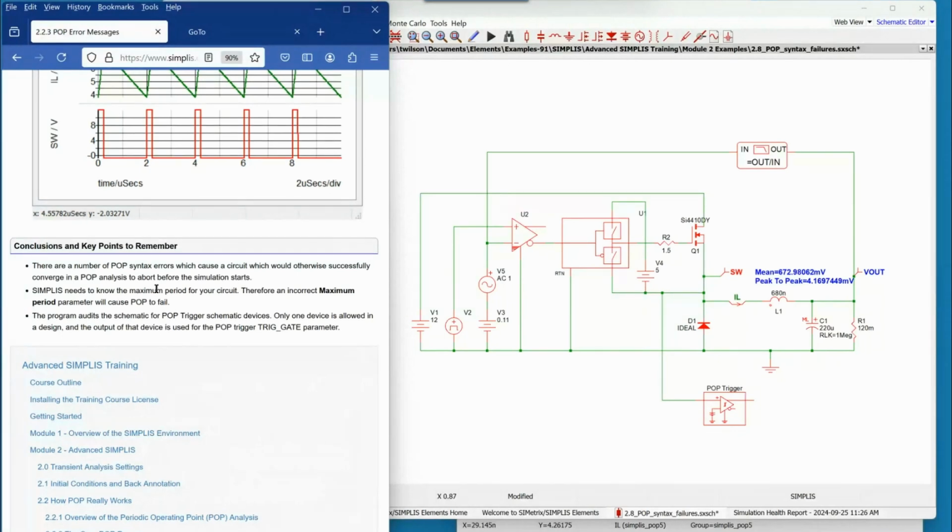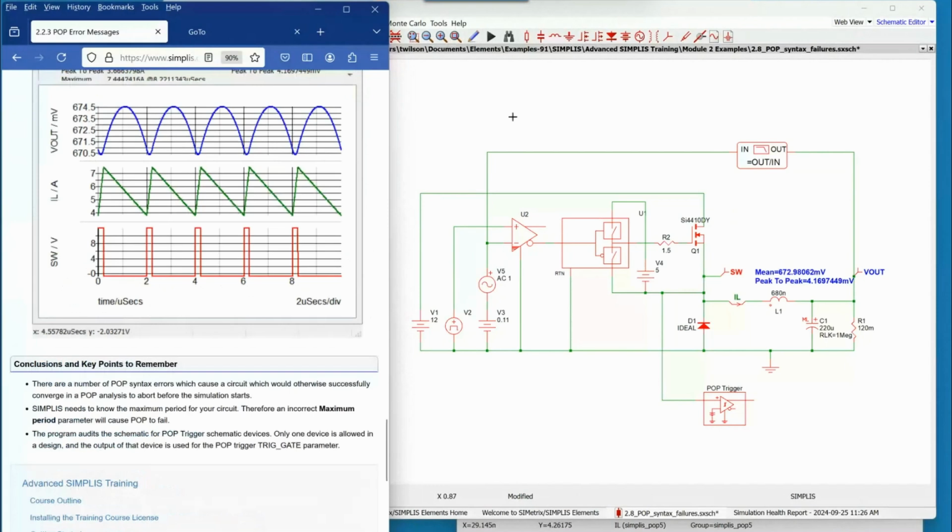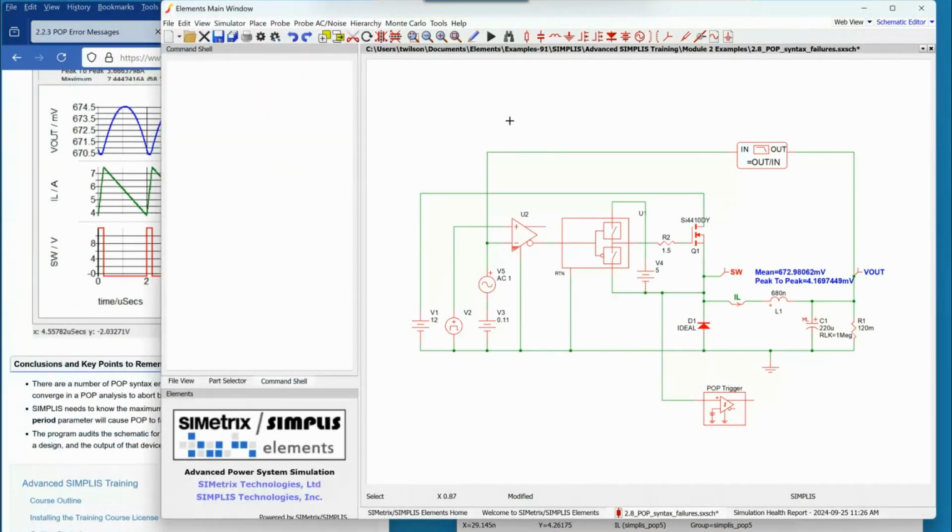Yes. You would not recommend putting it on a quiet node, not a power switching node as is shown on the schematic. Rather, the drive signal, for instance, or the clock signal would be cleaner. Something with a sharp edge. Ideally, as Chris mentioned, you'd like something that's always switching, so the clock is always going to happen.